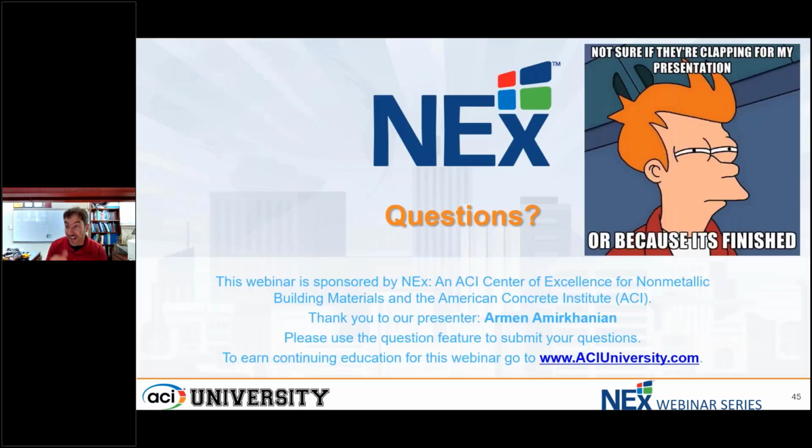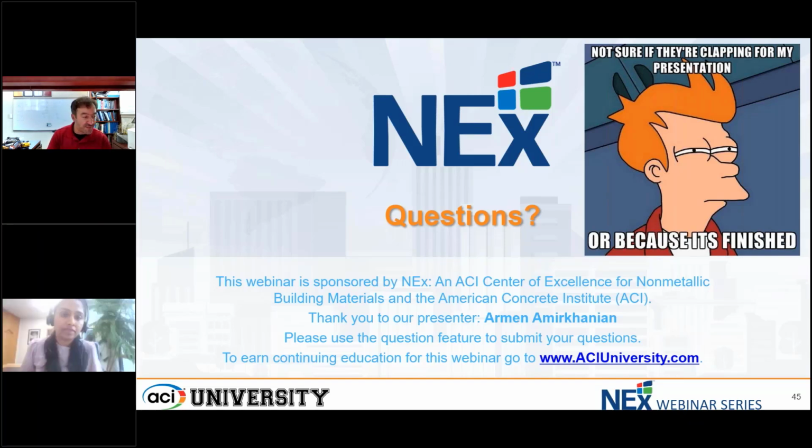All right, I'll leave this up, but I just want to tell this very short story. Federal Highway came out with a call a couple months ago requesting proposals for business economic development on big ideas to solve problems in transportation. So I sent them an email and said I have a solution to ASR, and that's literally what I put in the subject line, knowing at least they would read my email. I said, we'll spray the aggregates with silane.